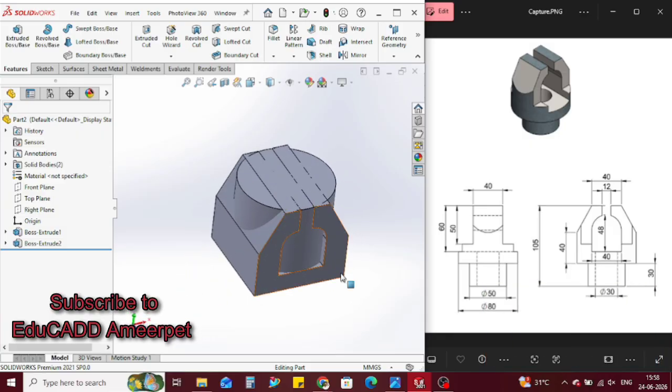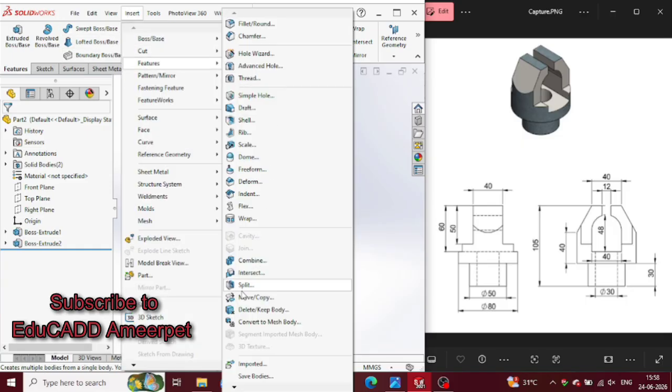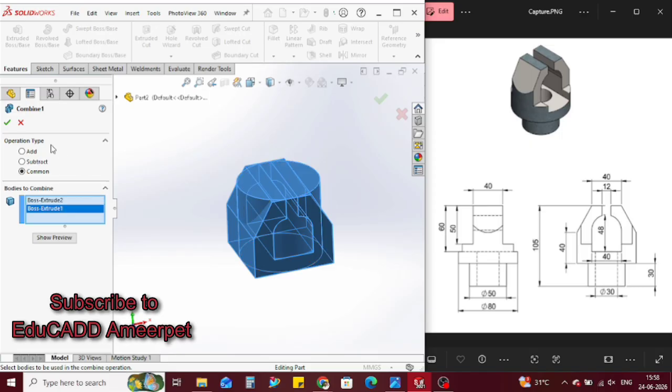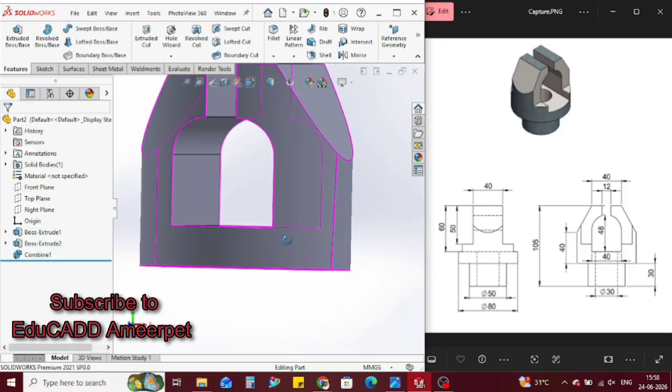After completion of this, if you want to make the two bodies a single entity, we have to use the combine feature. In this, we have to select the common. Simply select the two bodies and press enter.